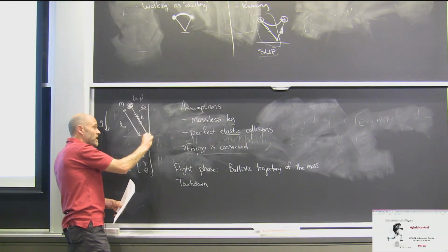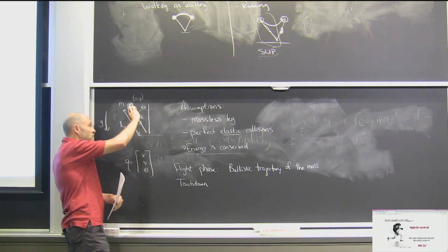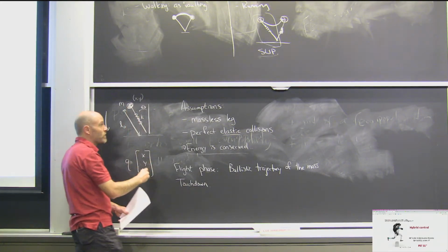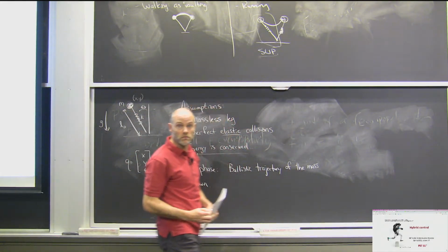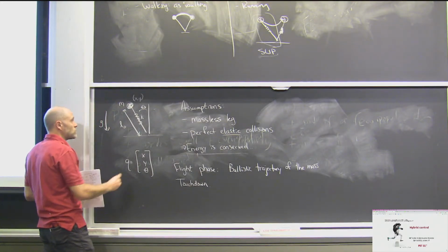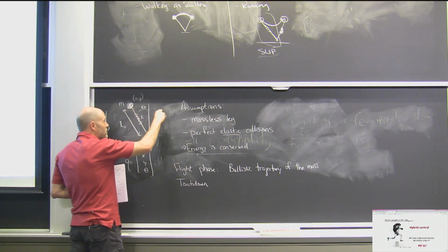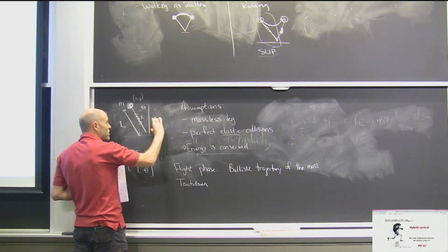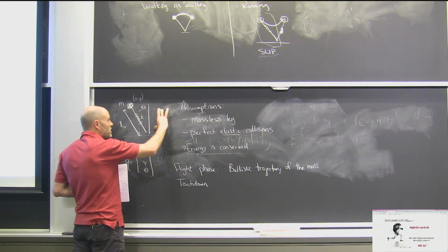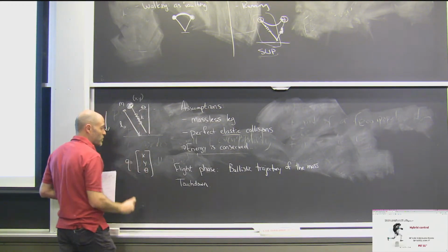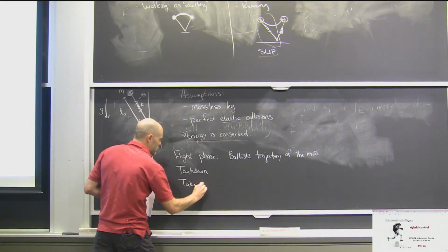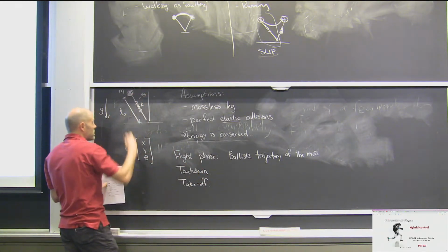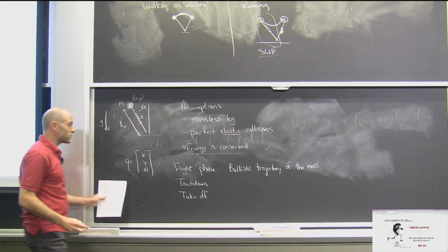I'm going to assume that I have a pin joint at the ground, that my leg begins to compress, and I'll go into this characteristic spring-loaded inverted pendulum dynamics. And like I said, when I come back out, the leg will extend until it reaches its rest length, and then we have this takeoff back to the ballistic flight phase again.